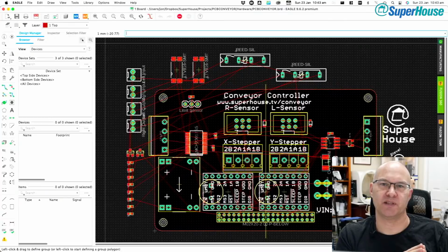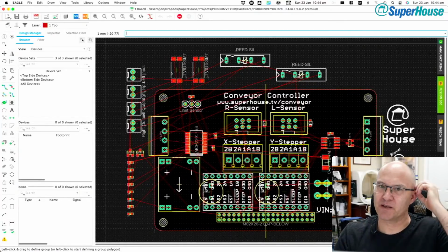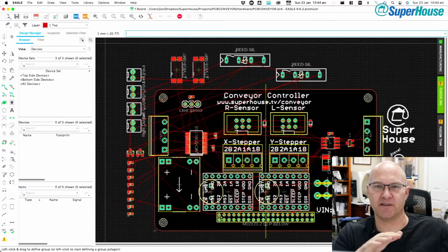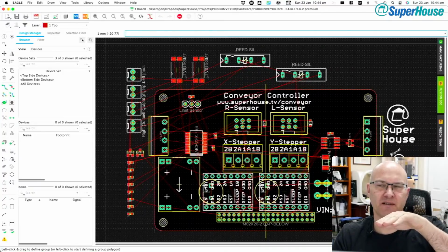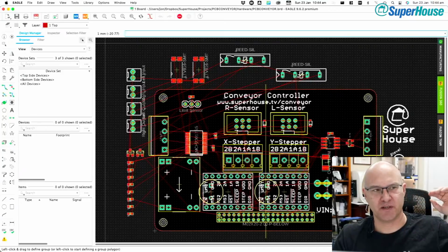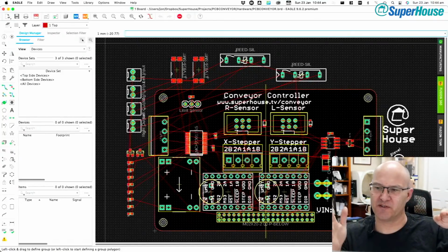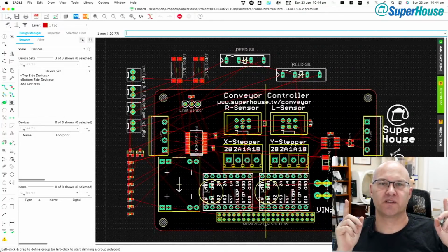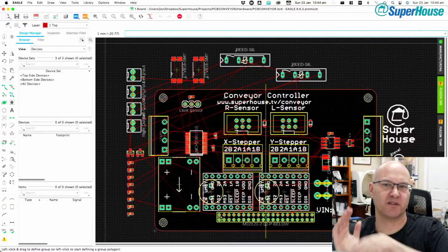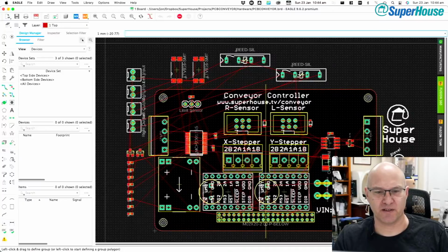And with a DC motor without some kind of a feedback loop, you can't really do that, because I could be PWMing the motor and have the conveyor moving at a certain speed, but you're still only guesstimating where it is at any point in time. So if you have a sensor that detects the PCB has come onto the conveyor belt and you want to move it to the 27 centimeter position, all you've got to go on is time. You can just run the motor for a while and then stop it and hope that you got it at that position, but it's not going to be very accurate.